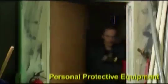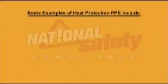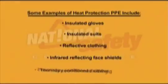Personal protective equipment. The use of some PPE, such as certain types of respirators and fire-resistant clothing, can increase the risk of heat stress. Workers should be monitored by establishing a routine to periodically check them for signs of overexposure. In other situations, special cooling devices can protect workers in hot environments. Some examples of heat protection PPE include insulated gloves, insulated suits, reflective clothing, infrared reflecting face shields, thermally conditioned clothing,